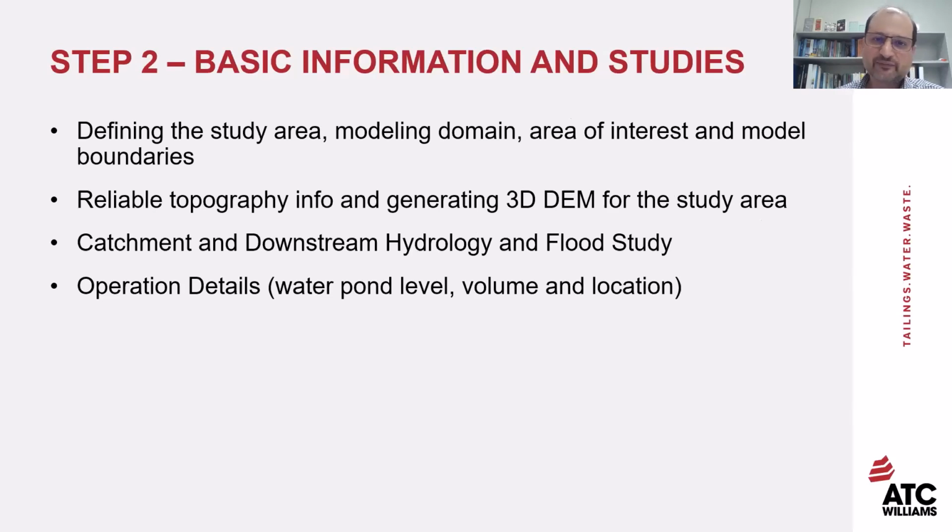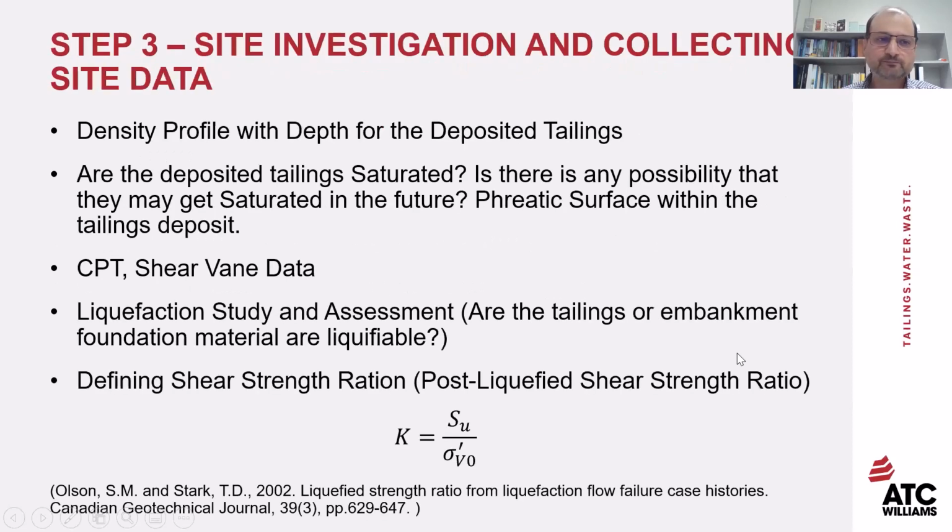Step two would be basic information and studies, including defining the study area, modeling domain, area of interest, and model boundaries, reliable topography information to develop the 3D digital elevation model for the study, catchment and downstream hydrology and flood study, and the details of the operation, including normal operating pond level, maximum operating pond level, and volume and location of the pond in the TSF.